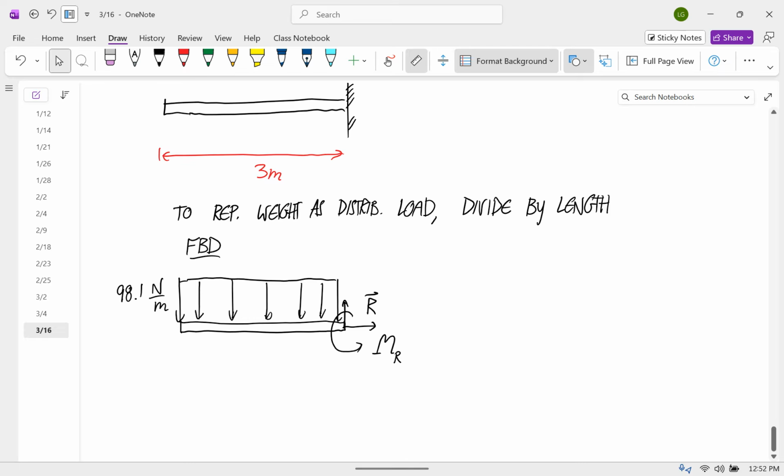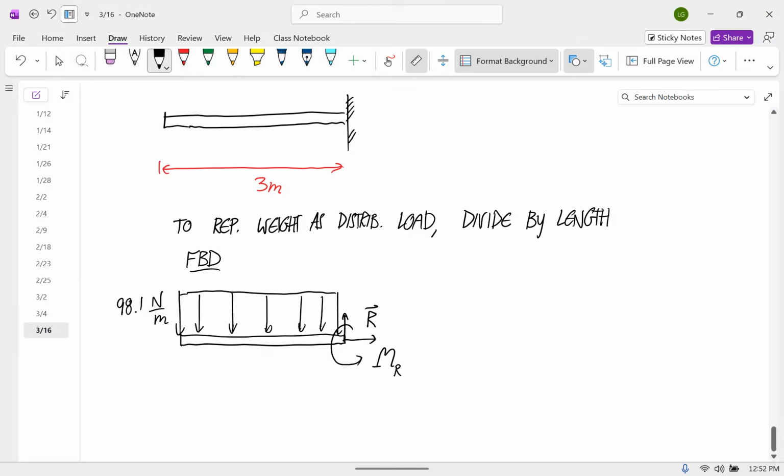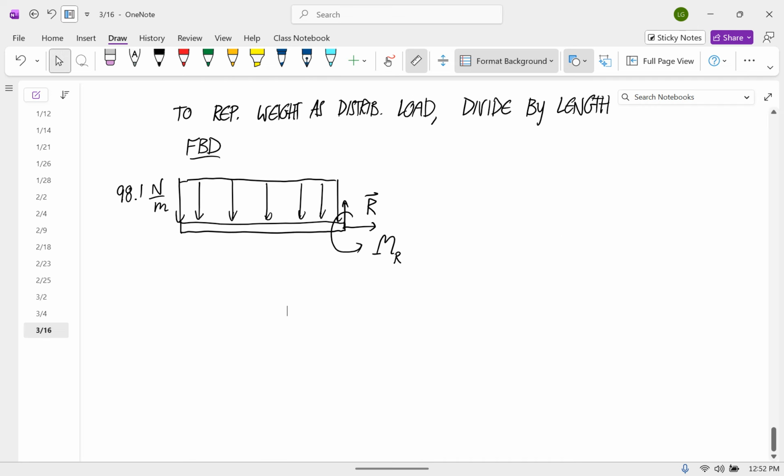Well, this is one where, I say the first step is to calculate the external loads, but if all the unknown external loads are at the far right endpoint, then they're not going to come up in the cuts. So we can just jump right into the cuts on this one. So how many cuts are we going to have here? Only one, that's right.